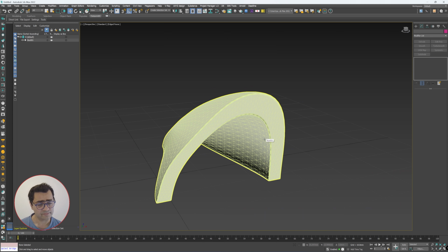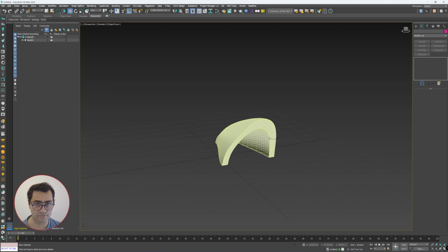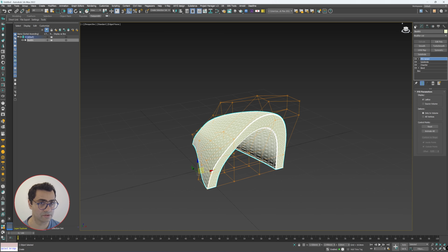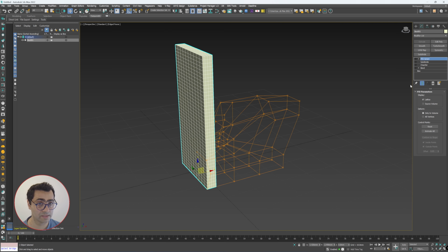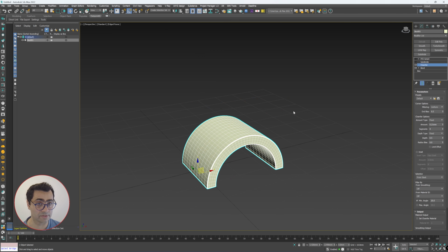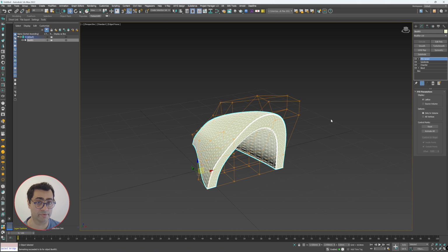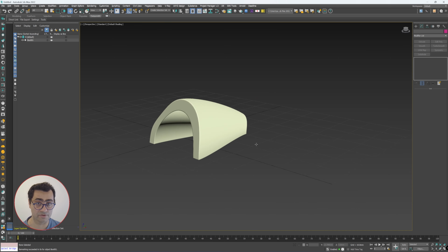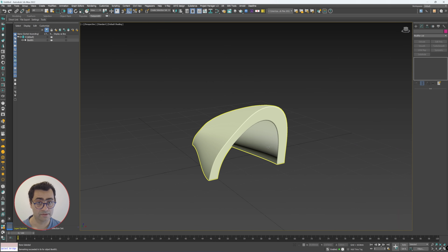Okay, so what we've covered, basics of how to actually create stuff in 3ds Max. So we started off from a box like so, and then we went up, we did the bend, added the chamfer on the edges, subdivided it, and then performed FFD operations on top of it, and we ended up with that sort of a structure. Okay, so you can quickly create some really complex elements by using this method.